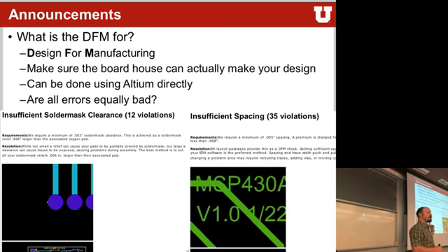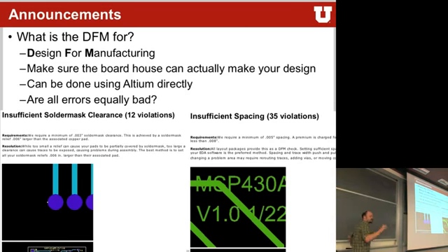Now, that said, sometimes you actually want to do that. So what happens in the design is the following. If you look at it in the physical structure, you have your PCB that sits here, right? This is FR4 material, which is fiberglass. That's the stuff that's in between the sandwich. Up on top, you have a copper trace, or a hole, or something like that. And then on top of this, they put the solder mask to basically make these things not conductive to the outside, so you can actually touch them without actually touching the metal. So if it's just a trace, you get covered up like this. That's what we want.